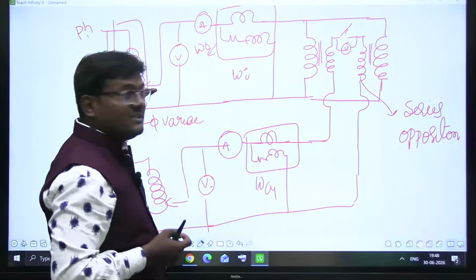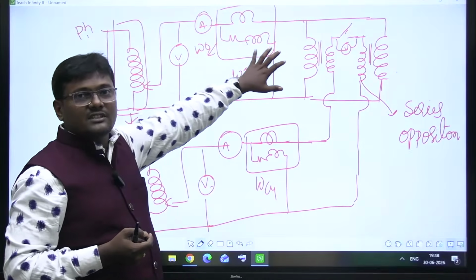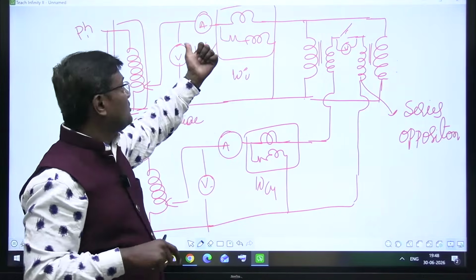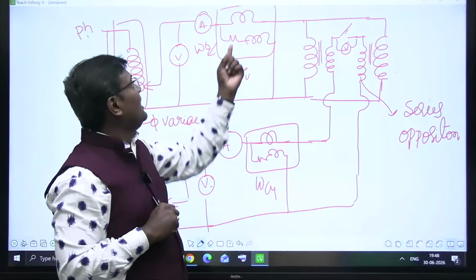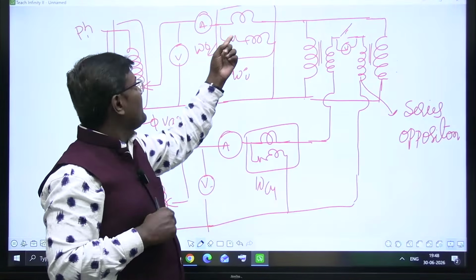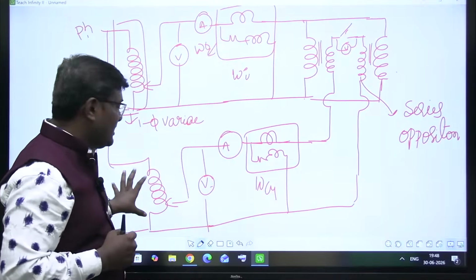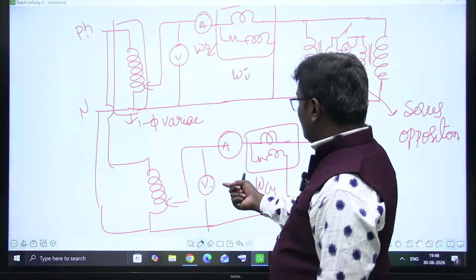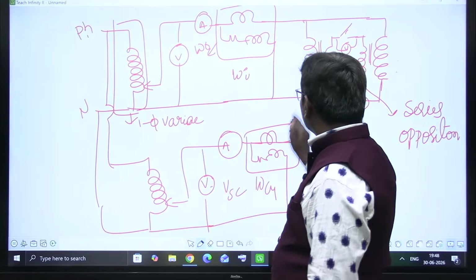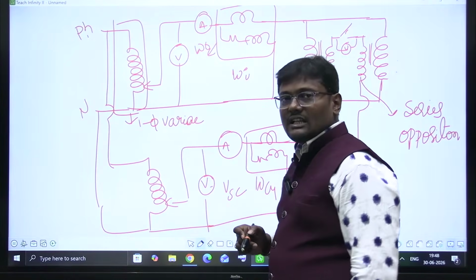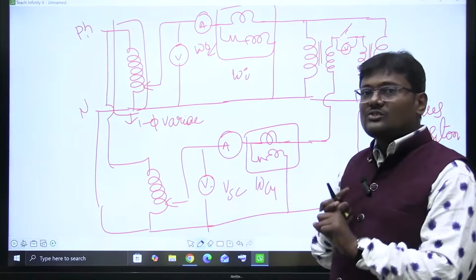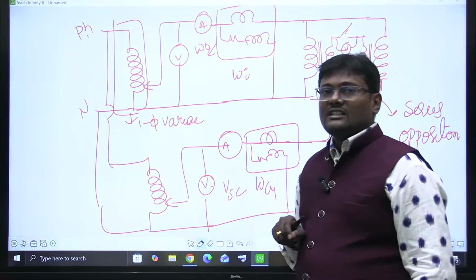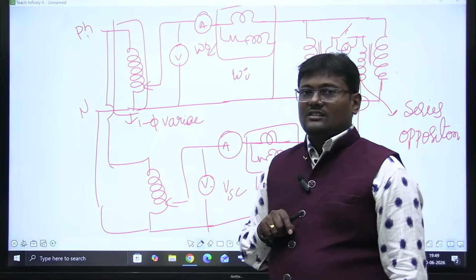Vary this auto transformer and apply the rated voltage, and observe the no load current of the two transformers. In parallel the voltage is the same, only V, and the iron losses of two transformers. Then vary the booster transformer and apply VSC, observing this voltmeter. If this voltmeter shows 0, then close the switch, and this current is the rated current, because both are connected in series.